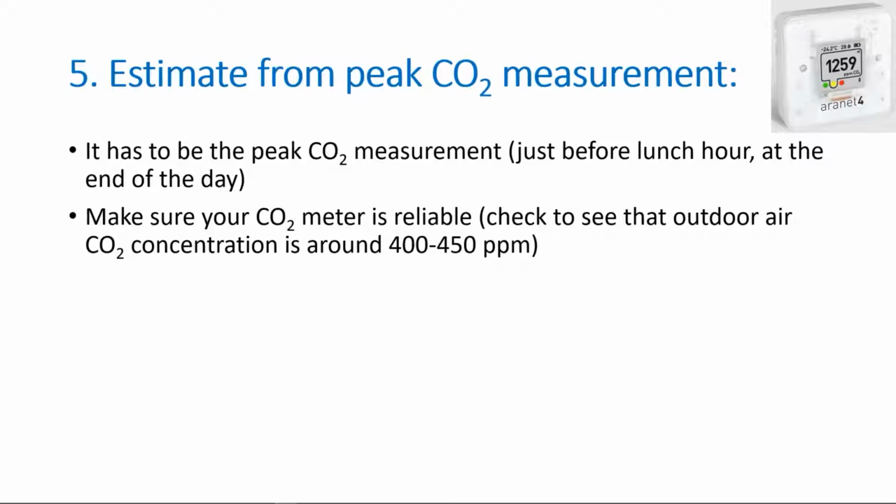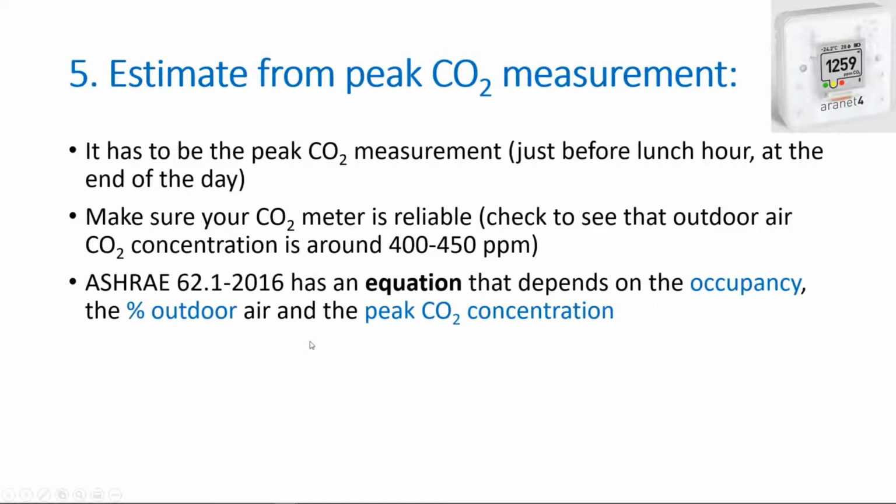If you want to check, what I did is I took a clear plastic bag and went outside, filled it up with outdoor air and put the unit inside, and then tied it off and brought it inside, let it warm up, and then your outdoor CO2 level should be somewhere between 400 and 450 parts per million. It may be higher if you have a busy highway beside you or something like that.